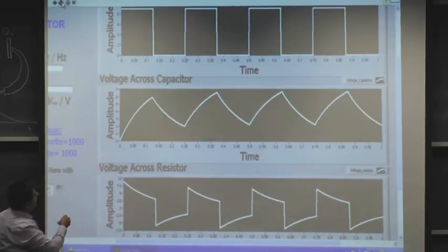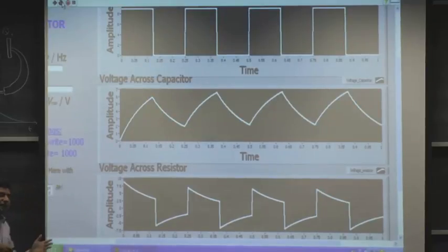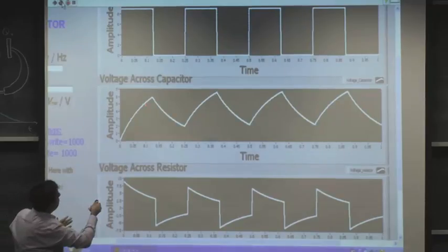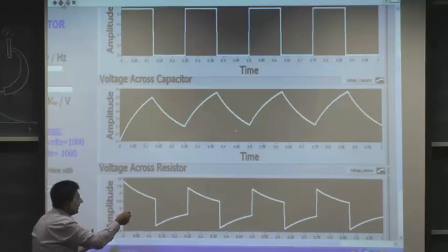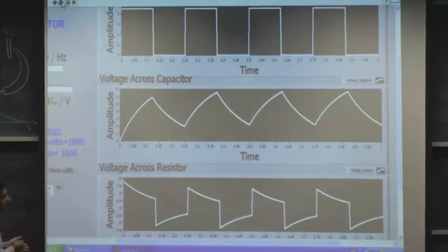So this is a waveform of the voltage across the capacitor, which is also synchronized with the charge across the capacitor, because the voltage is just proportional to the charge. So charge is building up and it's decaying, building up, decaying, building up and decaying. And now let's look at the current. This is just the current through this circuit, because this is the voltage across the resistor. Now the current is decaying. As the voltage across the capacitor builds up, the current decays, exactly in line with what we see here. The voltage goes up, but the current goes down.